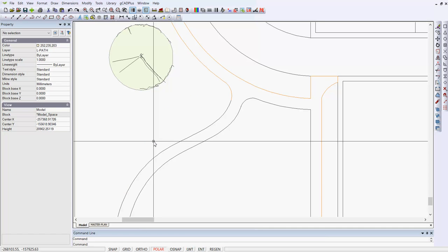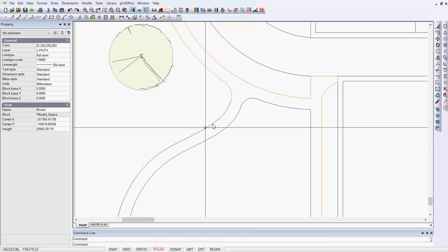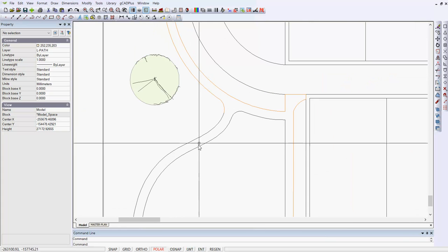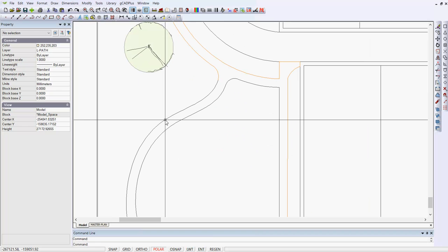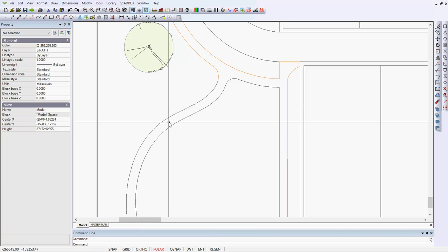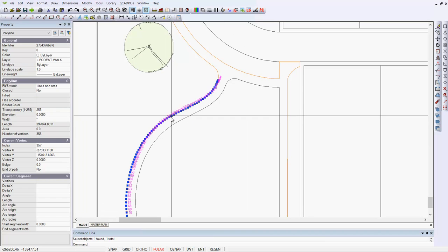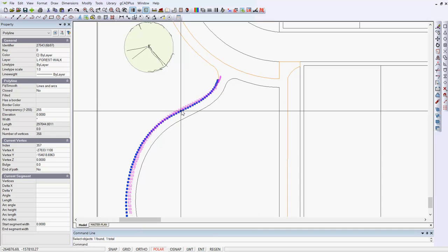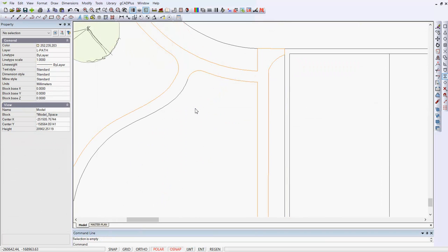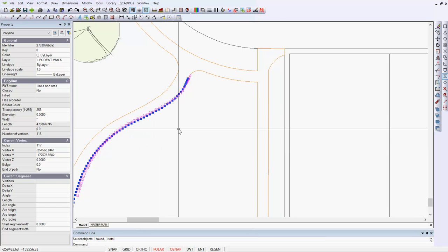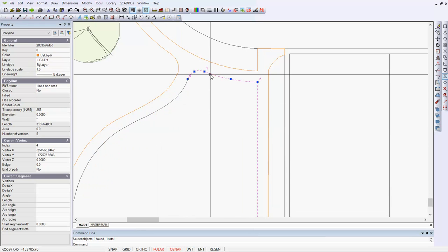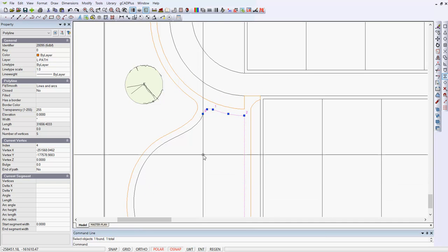We want a polyline there, so we want to put a new polyline in the path, and we want to rub out this particular one here. So that's the next stage of the operation. We need to change this and put it into a new form. I have exactly the same problem here on the internal part here. Here's another one of these exploded polylines, and I'm working my way around the internal zone in here.